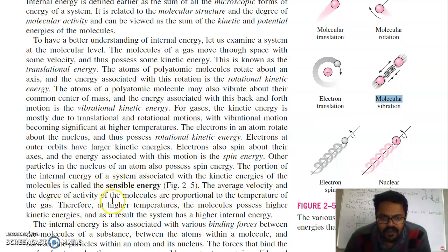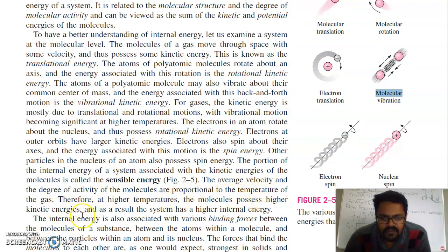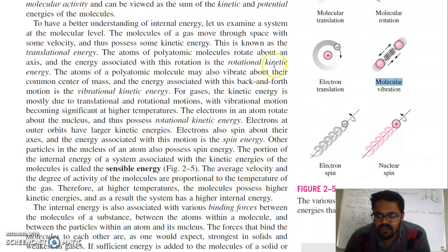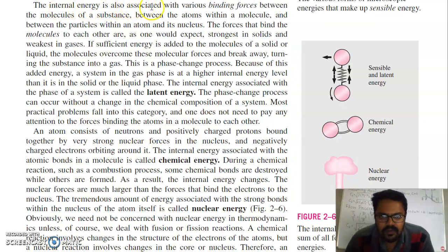The average velocity and degree of activity of molecules are proportional to the temperature of the gas, meaning whatever energy these molecules contain is reflected in the average temperature of the gas. Therefore at higher temperatures the molecules possess higher kinetic energy, and as a result the system has a higher internal energy. So internal energy is a function of temperature: the higher the temperature, the higher the internal energy. The internal energy is also associated with the various binding forces between molecules of a substance, between the atoms within the molecule, and between the particles within an atom and its nucleus. The forces that bind molecules to each other are, as one would expect, strongest in solids and weakest in gases.